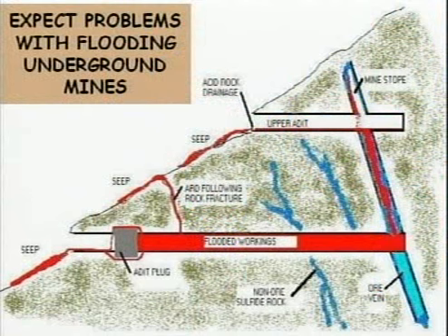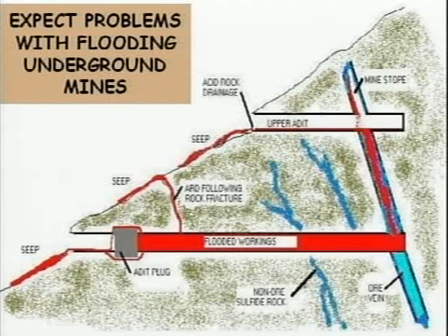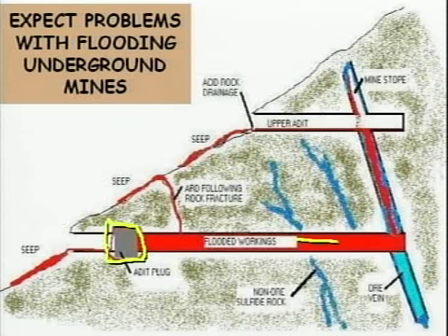Many abandoned mines are drained by tunnels that provide a constant loading of ARD on a watershed. This cross-section layout of a typical hard rock tunnel shows some of the effects of intentional flooding as a remedy for ARD. Here's the plug right here. Plugging adits is a special case of ARD waste flooding that needs to be considered very carefully. The sulfur salts and byproducts of pyrite oxidation will be typically present back in the old mine workings and could create a large mine pool with ARD characteristics unless there's a source of alkalinity to counteract it.